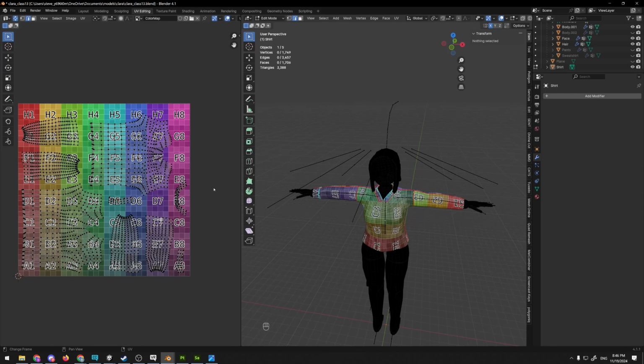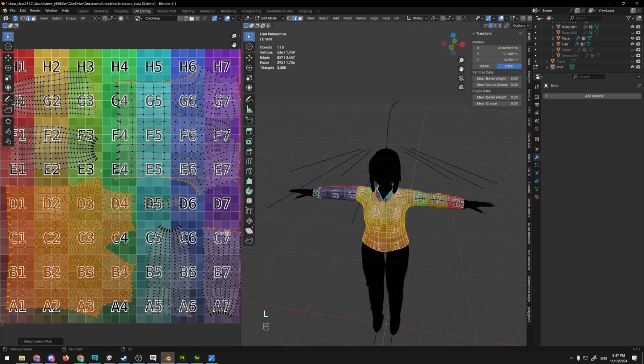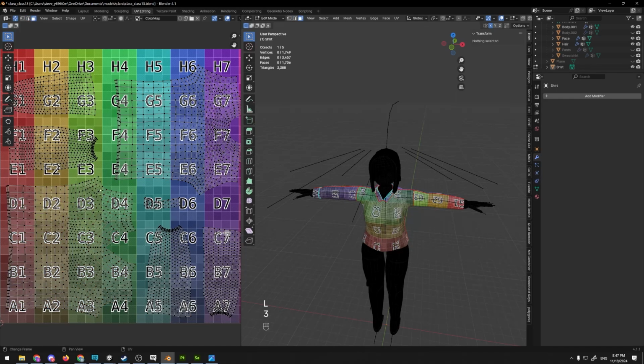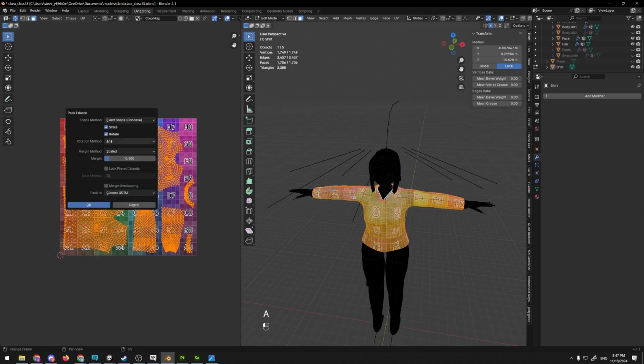The reason why you want a little bit of space is because your texture density is finite and relatively small. Typically, you're working with a 1K or a 2K texture, which means you have either 1,000 by 1,000 pixels or 2,000 by 2,000 pixels. It's powers of 2, so it's 1024 and 2048. If you have your UV islands too close together, you might suffer from texture bleed, which is the idea that if you have a completely different texture on one island than the other, and you put them too close to each other, you might start to see the texture from one island on the other, and that can be a problem. So having at least a little bit of margin is good when you pack your islands.